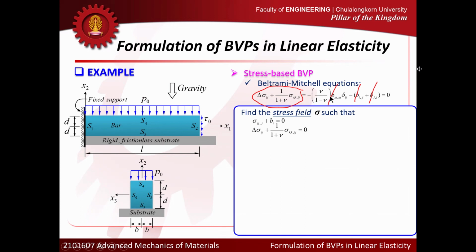And for this particular case, the term involving the body force field is eliminated, because body force is constant. This equation has to be satisfied for every point X in the body. And I also need the boundary condition as well. For the surface S1, this is the difficult part.